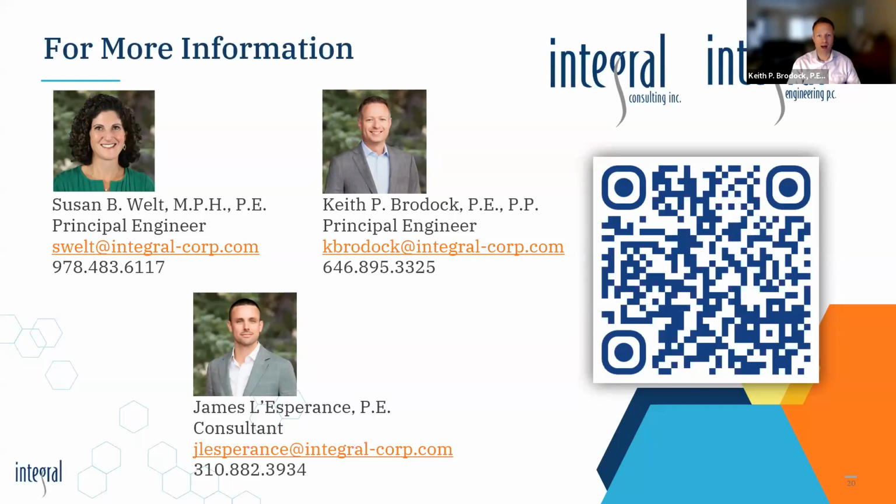we're much more likely to have groundwater in contact with our building slabs. And as we just mentioned, a subslab depressurization system is meant to apply negative air pressure below the slab. But if there's no air below that, because now we're having higher groundwater, that can really mess up a subslab depressurization system or really make it not operational.